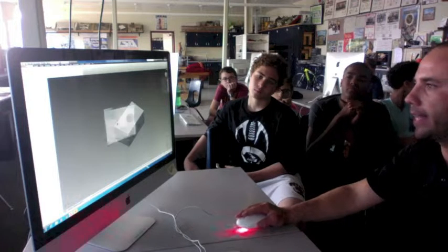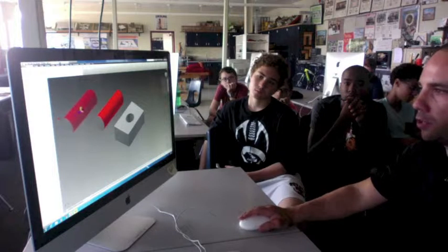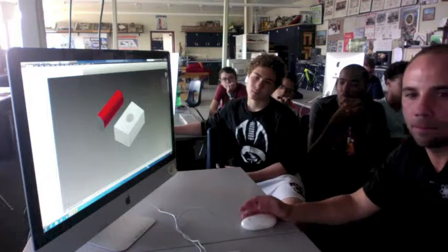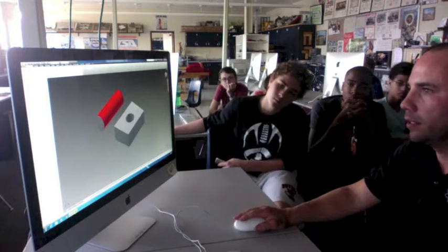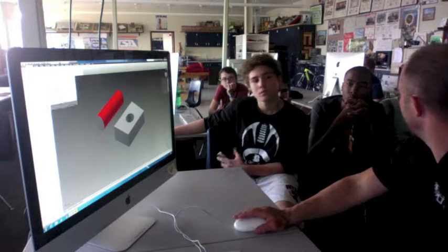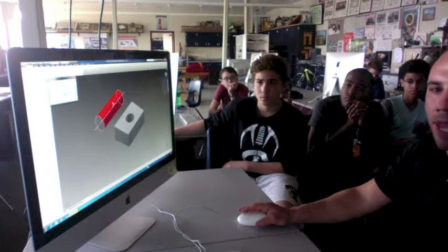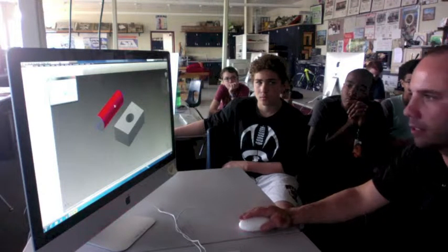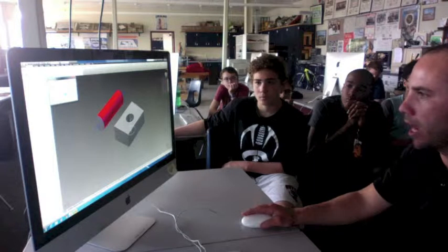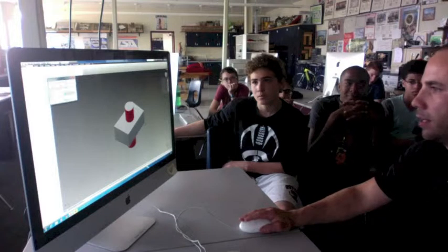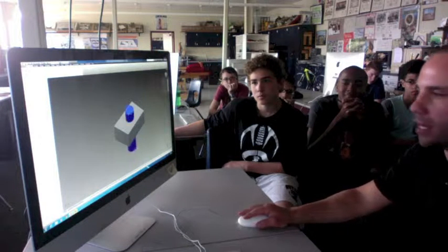Now I'm going to go to place again, and I'm going to pick the cylinder. And I'm going to show you how to correctly constrain this cylinder to the block so it goes in the middle. Okay? So this is really, really quick. I will go over this again in greater detail if you need to individually. But I'm going to go to constrain command, and I'm going to pick the mate. I'm going to pick the mate command there, and I'm going to pick the hole on the block, and it automatically inserts it in the hole. And I hit apply. And now I can still drag this up and down.